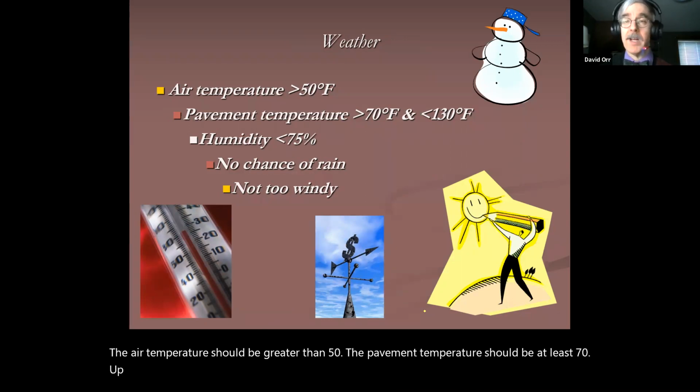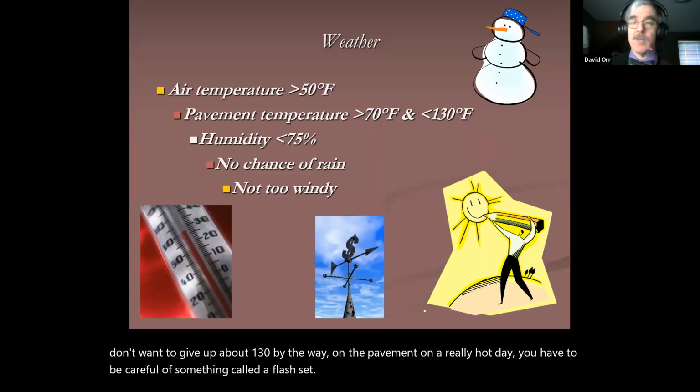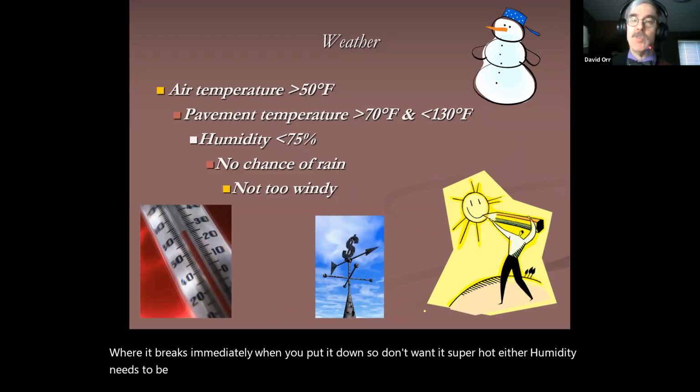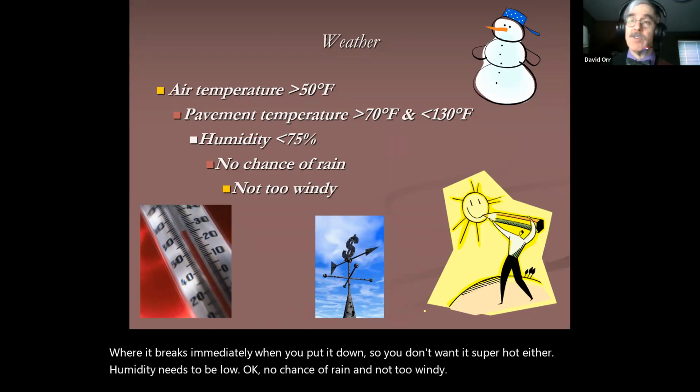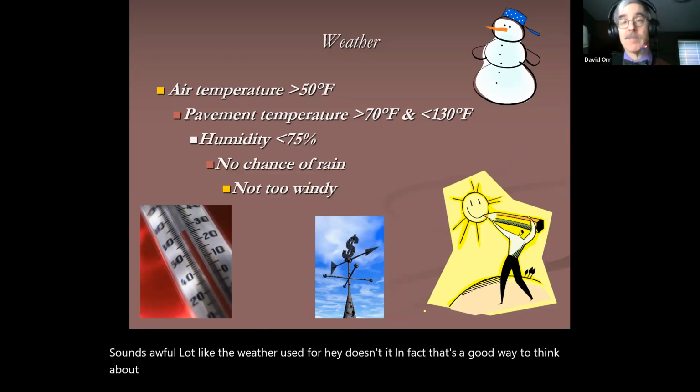Don't want to get above about 130, by the way, on the pavement. On a really hot day, you have to be careful of something called a flash set, where it breaks immediately when you put it down. So you don't want it super hot either. Humidity needs to be low. Okay? No chance of rain and not too windy. Sounds an awful lot like the weather you use for haying, doesn't it? In fact, that's a good way to think about it. If the weather's good for haying, it's probably pretty good for doing wearing courses.